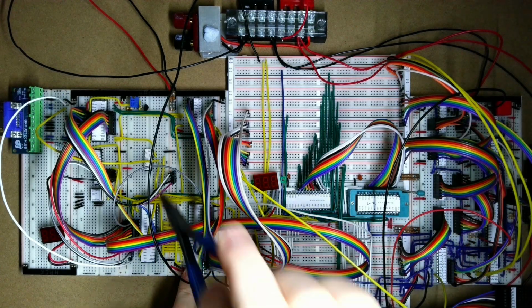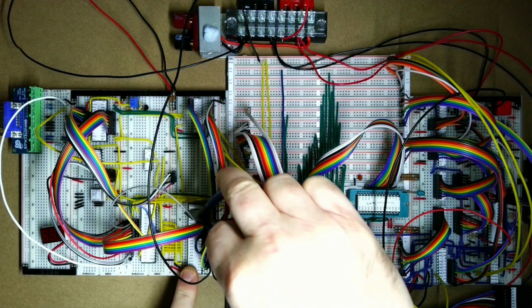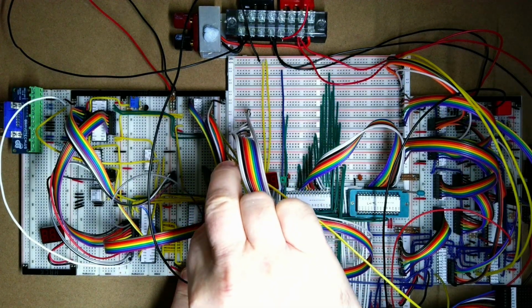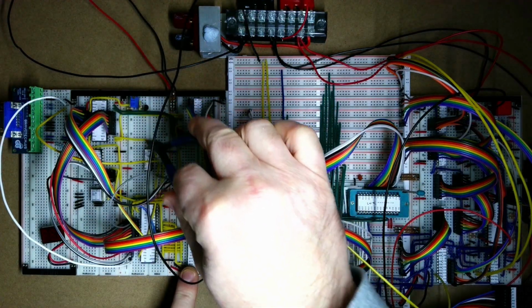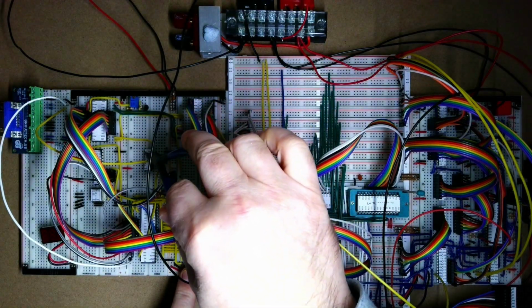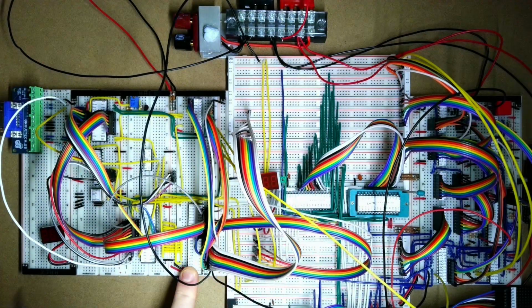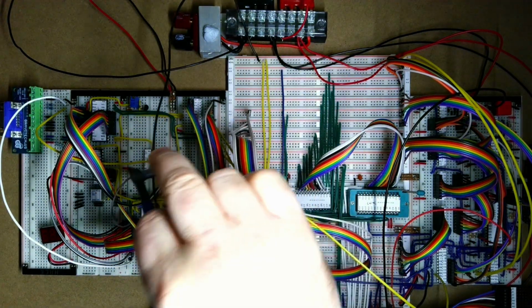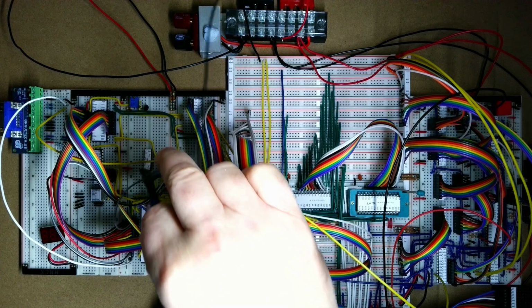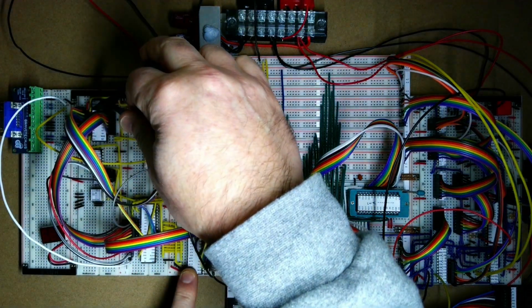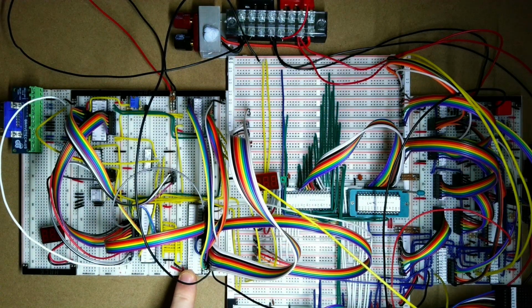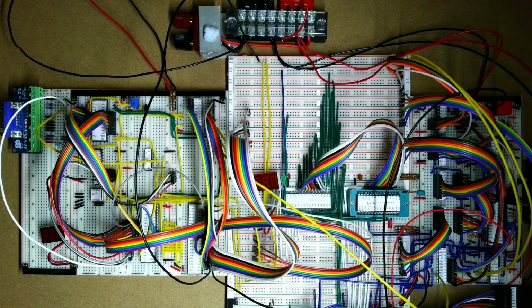So we're going to be adding the character latch down here, and it's going to have output from here coming to this side. Then outputs from there are going to go to the character generator EEPROM, which will be up here. So we're going to need to move this inverter, probably just move it over here for now. And then the shift register is going to go in here. The output from that shift register we're just going to use to drive one of the P0 to P4 inputs on the video DAC. What that should allow us to do is output the characters.